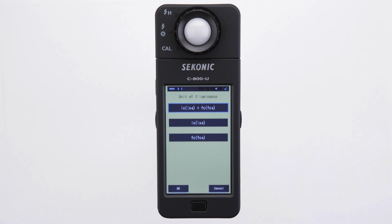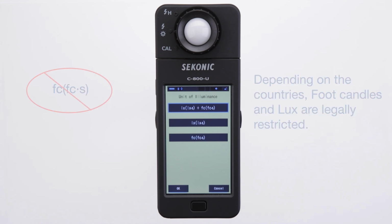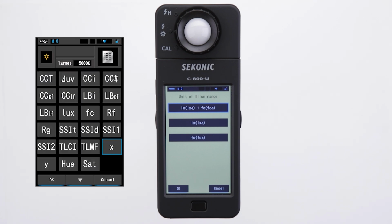In some countries, the C-800 doesn't display illuminance and exposure in foot candles and foot candle seconds due to legal restrictions. In this case, the unit of illuminance button will not appear in the settings screen. While you're in the measuring screen, you can select both lux only or foot candle only. This setting is located in the display item selection screen.